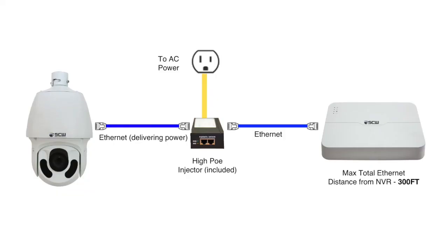That's not a problem. I don't have all the numbers in front of me, but as far as the full size and larger PTZs, those do come with an additional power source called a PoE injector that you need to put in line from your NVR to the camera. It's usually 3 or 6 feet away from the NVR side, and then it can run up to 300 feet on the Cat5e or Cat6 cable to the camera to provide the data stream and the power for that particular device. I think that covers everything.